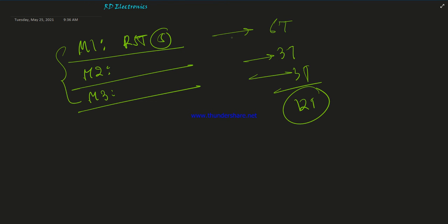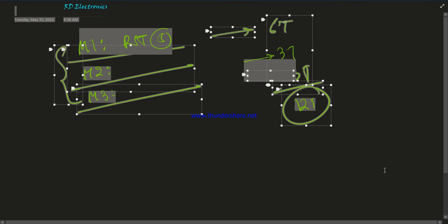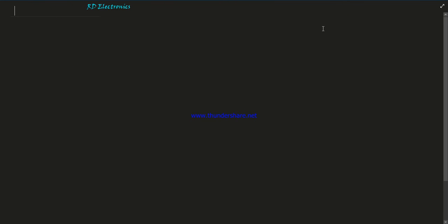Now we discuss another interrupt process, which is very important, known as the hardware interrupt or 8085 vector interrupt. Why is this known as vector interrupt? Because their call locations are fixed, they are not changing. For any developer, like Dynalog, like UP85, like any Intel or Philips, any developer which developed a microprocessor development board, these call locations do not change, because they are fixed.